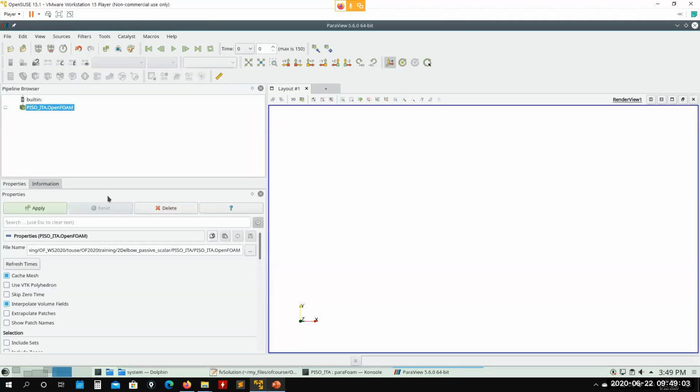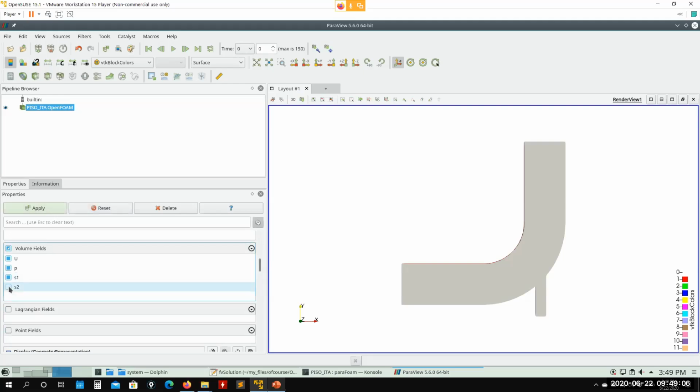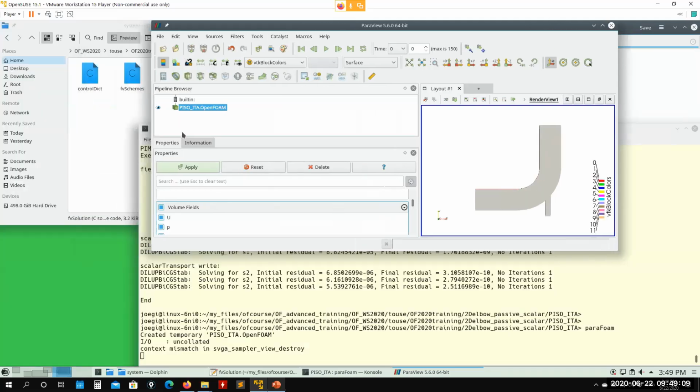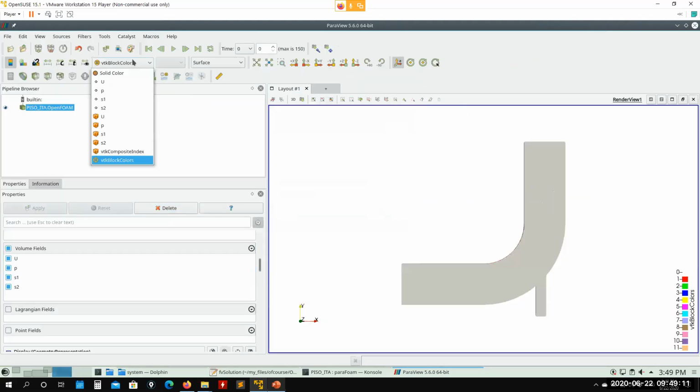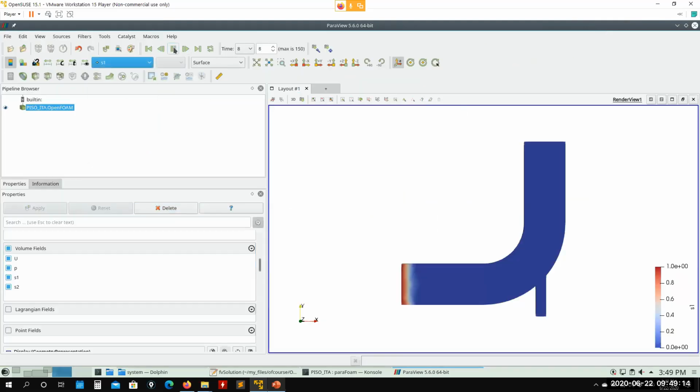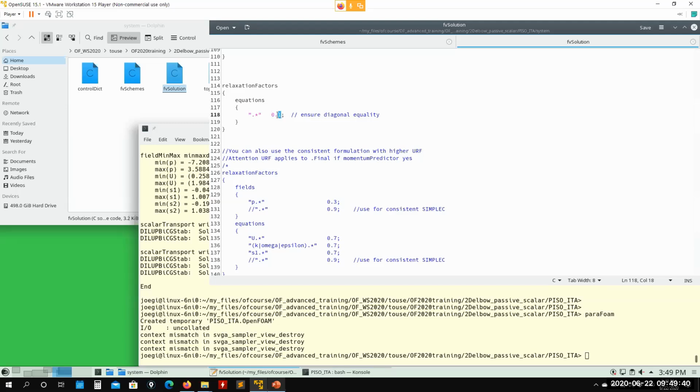So we have a solution here. Apply. And if I press play, see that now it is converging. There is no problem, but see that you lose your temporal accuracy. Maybe if you let it iterate up to 600, you will reach the same solution as the previous one, but this one is no longer time accurate. So this will be, let's say, a pseudo transient. My advice, put under relaxation and put here 0.7. You are not losing any time accuracy.